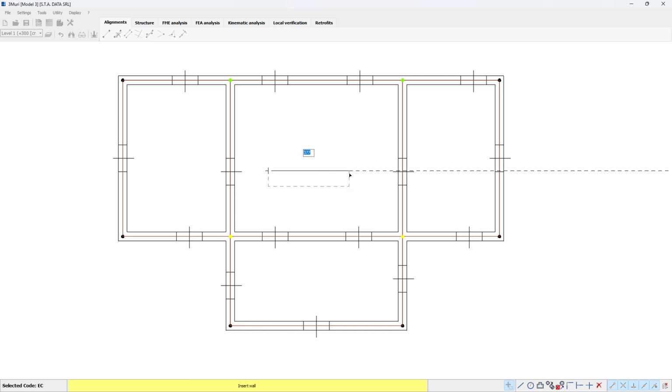As we see here, we just go ahead and select, and it's going to tell us the specific length of that element in the scale that we selected, and more graphical tools that we are going to use to draw our structure. And of course, we can turn the snaps on or off as we wish to do so. And we have more options for our alignments, such as we can delete them, we can offset them, very similar to many CAD programs in the industry.